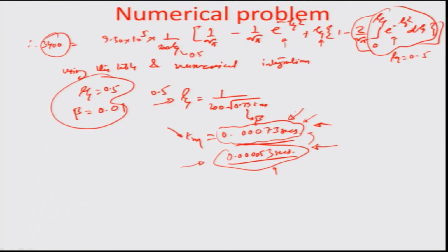In case you have a through cut, there is always a question of how much material needs to be ablated out till and until the melt zone can go all the way up to the depth of the workpiece that we have been considering. So the basic essence of the start of machining, and the wait period involved for the temperature to reach the melting point, is a very key thing in the whole laser machining process. Although it is not that big a number, it still matters, particularly in micro machining using